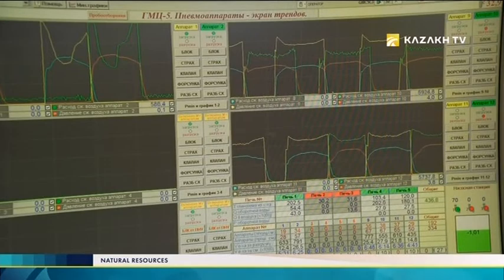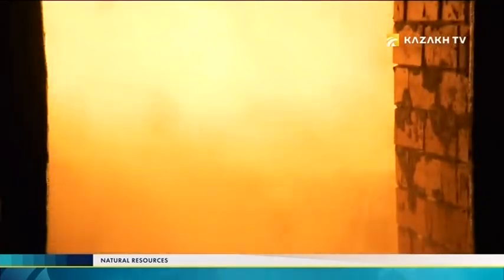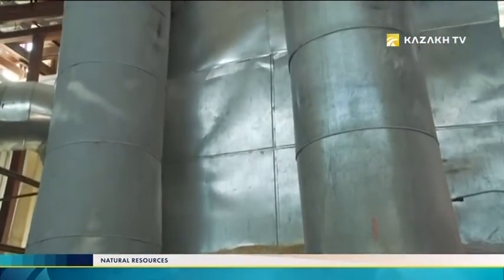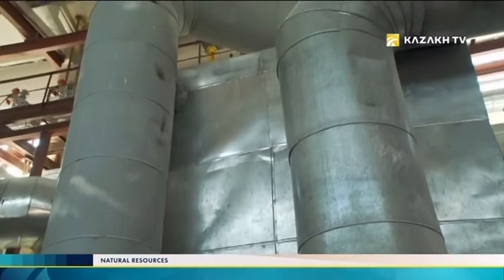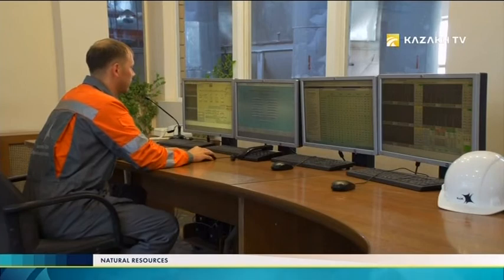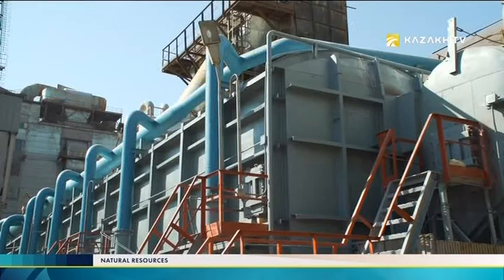As a result of using the parallel-serial mode of agglomeration, aluminate solution is produced here. After the post-filtration stage, the aluminate solutions are cooled down to 50–75 degrees Celsius and sent to decomposition stage, which is crystallization of aluminum hydroxide under certain chemical conditions.